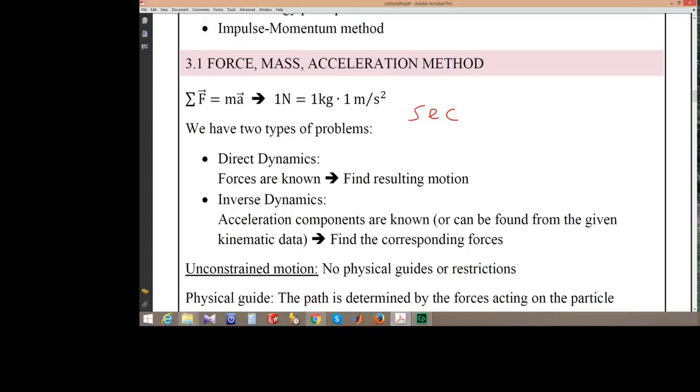So you use this information in your design purposes. Other than that, you find out the reaction forces, for example, and these reaction forces would give you the information about your design, to select your materials for the links, for example, in a mechanism.